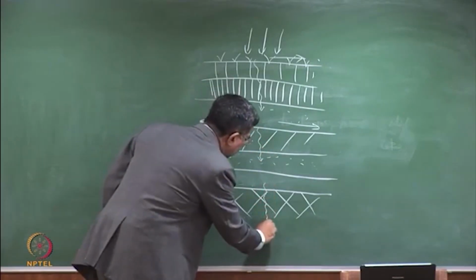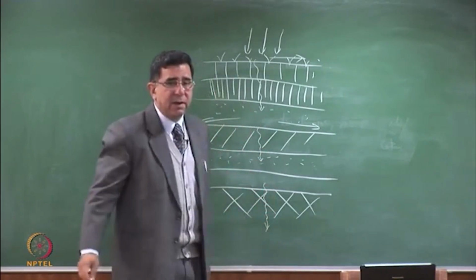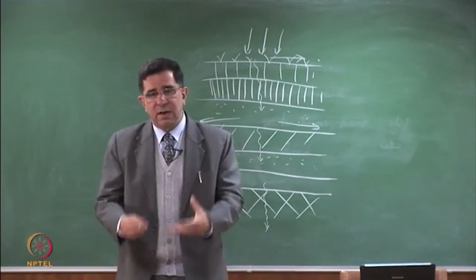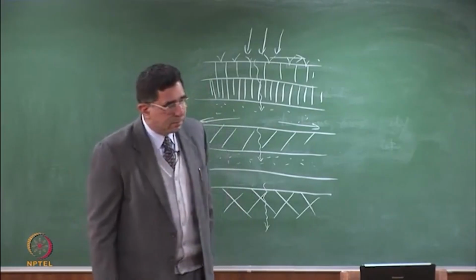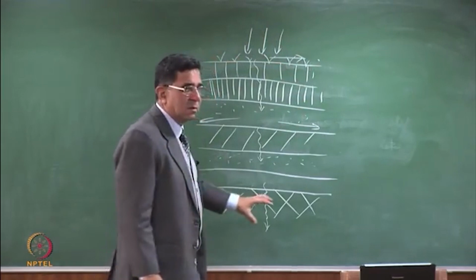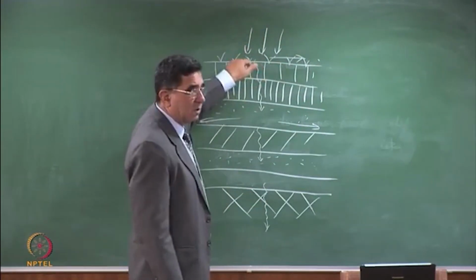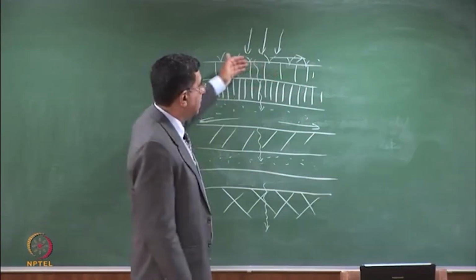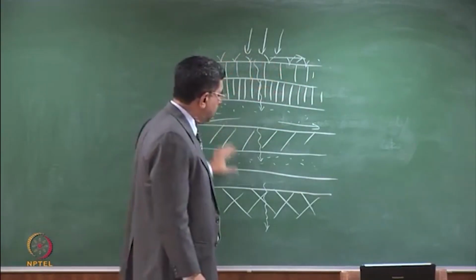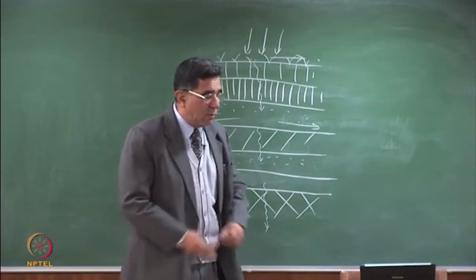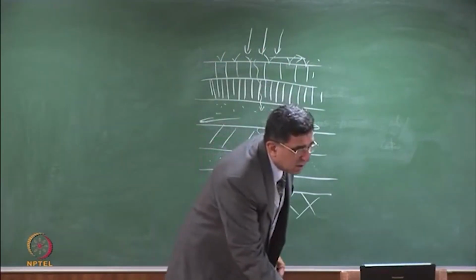This will percolate through the waste, and this waste may be several tens of meters thick, and then it will come to the bottom. So to simulate all this, how much is falling, what is the infiltration coefficient, what is the runoff coefficient, depending on whether it is grass or not, a lot of mathematical models have been developed, and one is listed here.